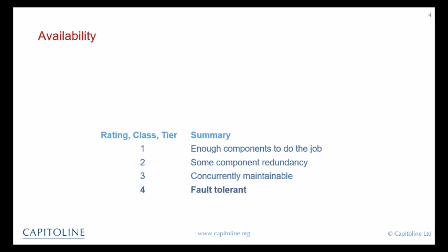And finally, the Tier 4 or Class 4 system is fault tolerant, so it will tolerate a single fault and automatically respond to that fault in such a way that the IT equipment will continue to operate even while that fault exists.